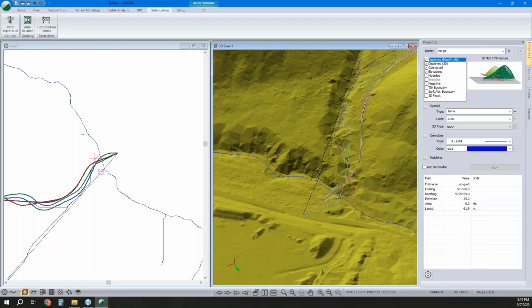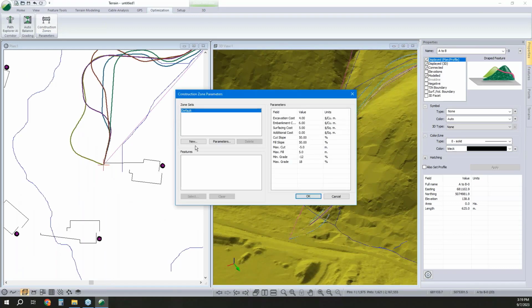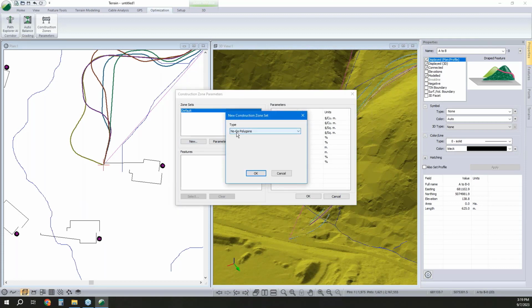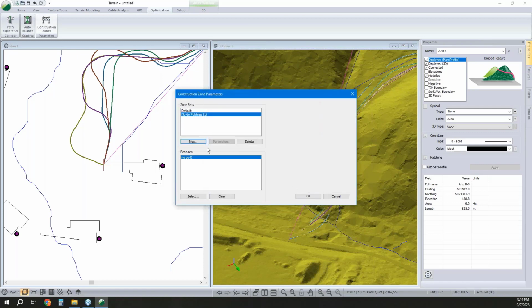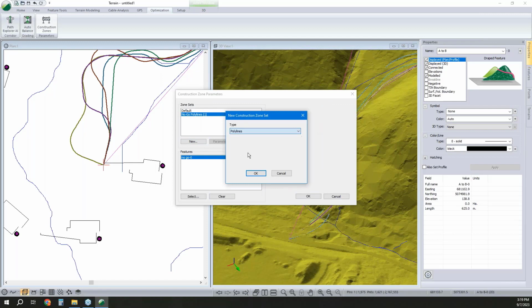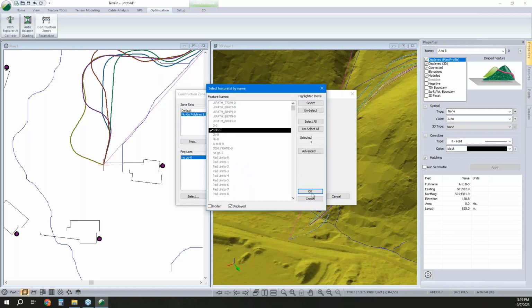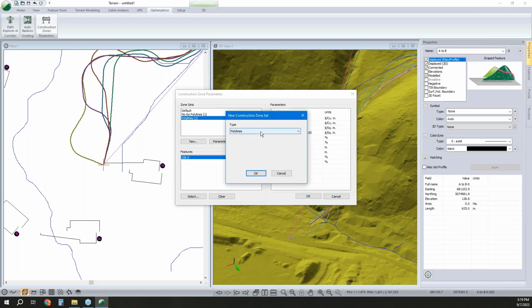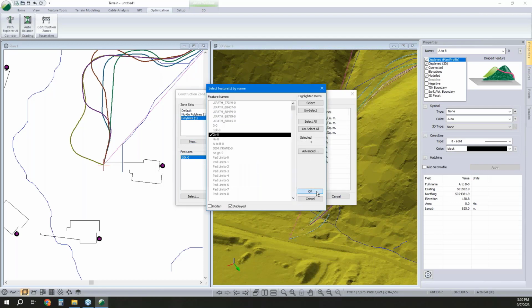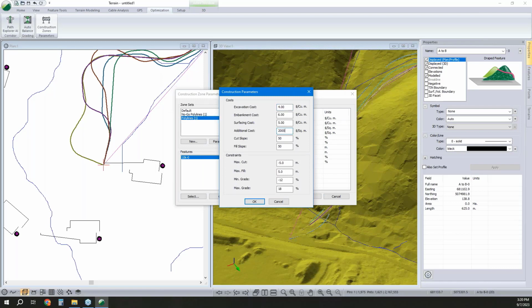All right, so we are going to add construction zones. We're going to come in here and we're going to say, well, let's create a new no-go polyline. So that's that one that I just called no-go. I'm going to say, well, let's make some polylines that cost a bit more. So our $10,000 one is going to have an additive cost of $10,000 per square meter for crossing. And we'll do that and we'll set, well, our 2,000 is going to be, you guessed it, 2,000.